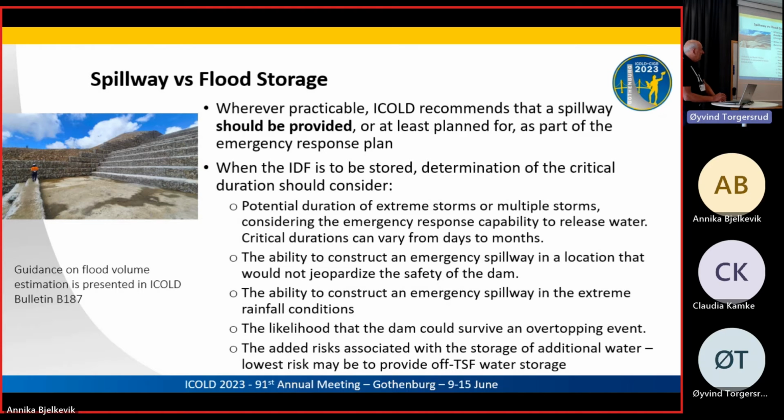And once again, if you do decide that you can live without a spillway, because it's quite difficult to put the spillway on in some cases when you've got a dam that's being progressively raised. It's easy to say, oh, don't worry, we'll just put an emergency spillway in if the flood level comes up near the crest. But if we're talking about extreme weather events, it's potentially impossible or impractical to actually do any work on a dam.